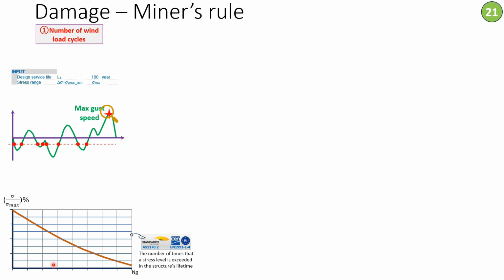The accuracy of the segmentation is based on how much accuracy the designer needs. You can go as far as 1% segmentation, 5%, 10%, whatever. So each segment represents a stress increment, 10% of the maximum stress, 20%, 30%, and so on, or 5, 15, 20, whatever accuracy is desired.